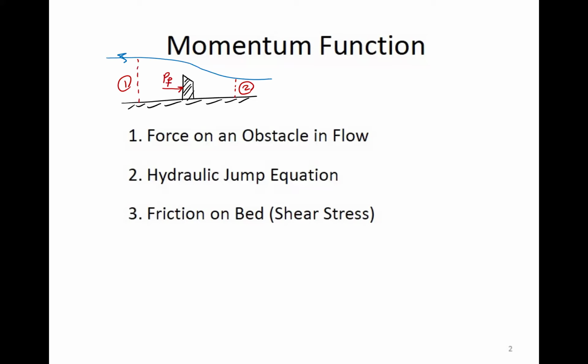In reality, we're looking at the force applied by the object on the control volume of the fluid, but they're the same magnitude, opposite direction. So nothing complicated. And then we said, in a case like this, the force divided by gamma is equal to the change in the specific momentum. So whatever we had upstream minus whatever we are left with downstream, M1 minus M2.